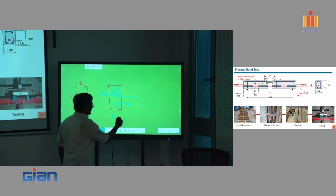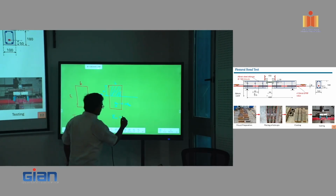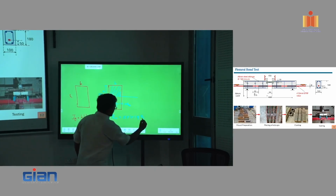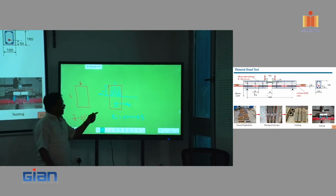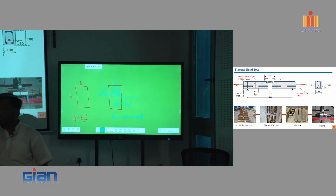And I cracked is typically about, I'm just giving numbers, of course, 15 to 20% of your IG, okay? Now, this is the least value after it is really cracked at the highest service moment, but I don't know the moment. Let's say my moment is only 30% of your ultimate.